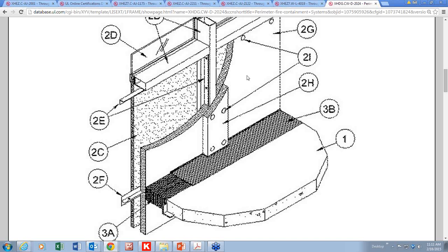This is one area that we're going to spend some time on later in the year, curtain wall design and fire resistance, because these are two big areas where fire can take place. Currently at ASTM, the standard for curtain wall only takes the interior fire spread of the assembly. So the floor can be two hours all the way to this point for fire spread inside.